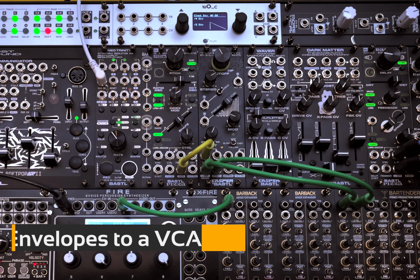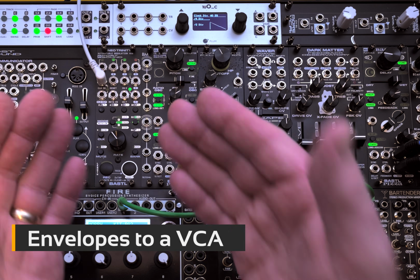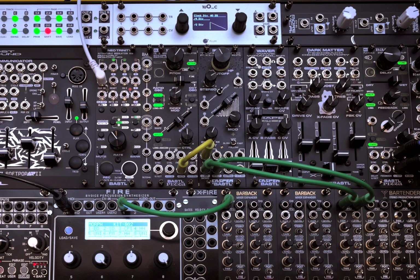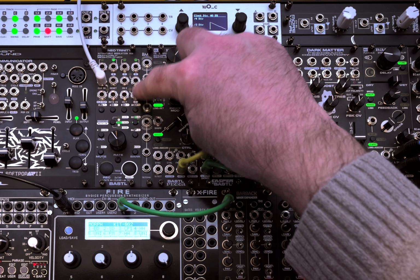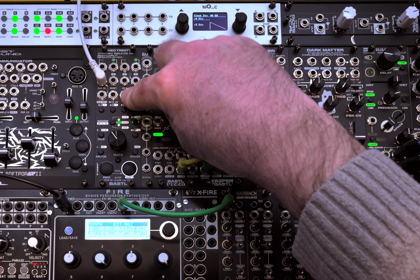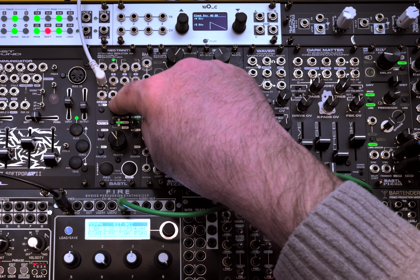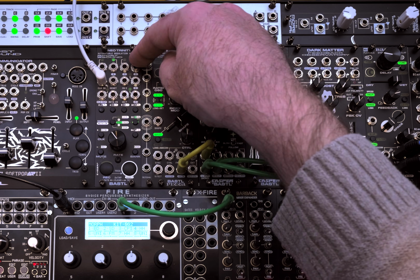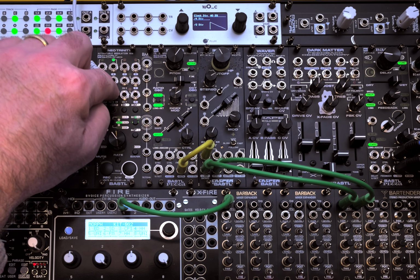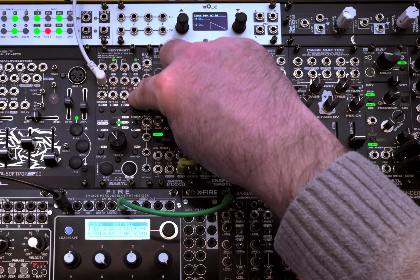Now let's look at how we can use the NEO Trinity to actually generate envelopes that you could send into a VCA, for example. Now to do this, you can only use channels E and F because they have input E and input F, so this is where you can send the trigger in. Though if you were to use the meta input channel, you would end up triggering these other channels, but then you lose control of other things using meta in. So I tend to keep that one for modulation, use these guys for your envelopes.